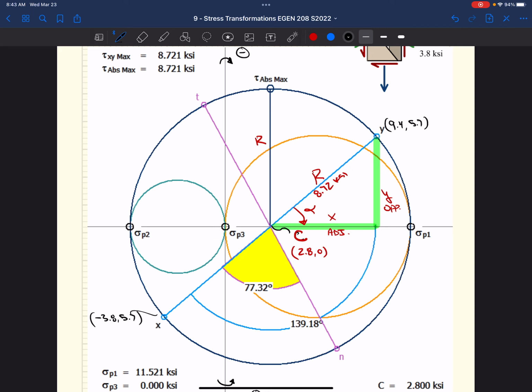So if you took a piece of chalk in your hand and you just twist it, it's going to fail in a spiral, and that spiral is going to be at a 45-degree angle. Because when you twist it, at that 45-degree angle, you're going to have a big compressive stress in one direction, and then in the other direction, you're going to have a big tensile stress. Right? It's actually going to be wanting to pull the chalk apart.